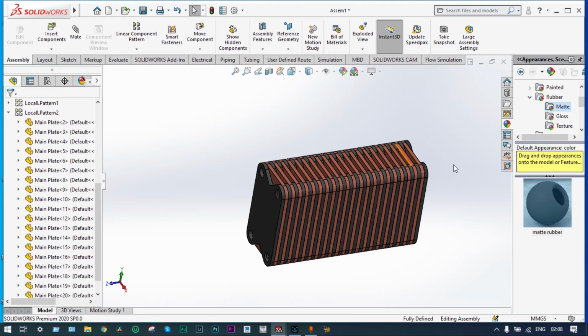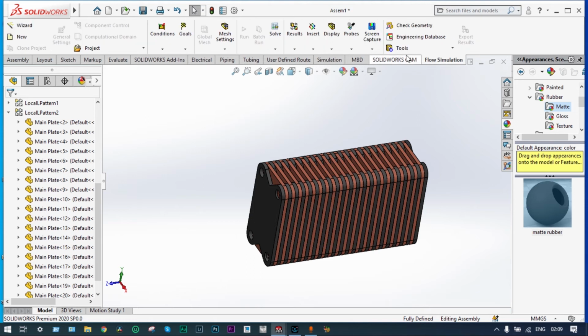Okay, so we're starting this one a little bit. We will not do analysis because it is already done in another video. Start flow simulation, and we want to provide the lids at the front gasket. Create lids. We have to select the surfaces for providing the lids.